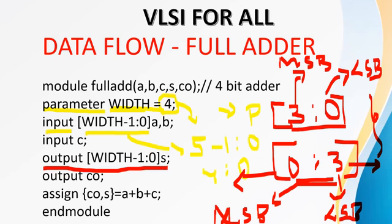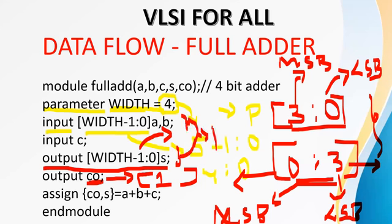Output also we have done the same thing. The sum can be of n number of width, but carry is only one bit. So we are not defining it as bit minus 1 down to 0, because 1 bit stores only either 0 or 1. But this can hold 1 0 0 or 1 1 0, something like that. Sum and this input, we give these two as parameterized variables. This is parameterized. So hope you all understood why we use the parameters. Got it?